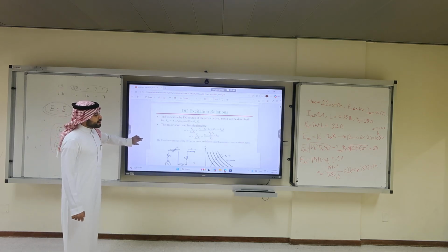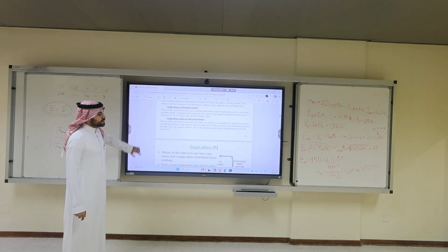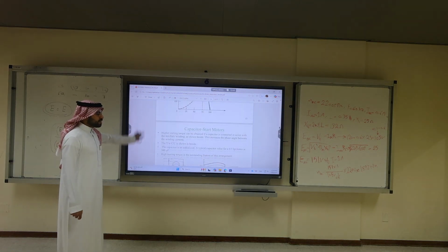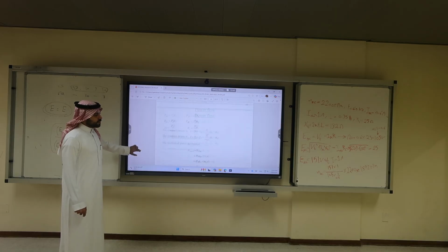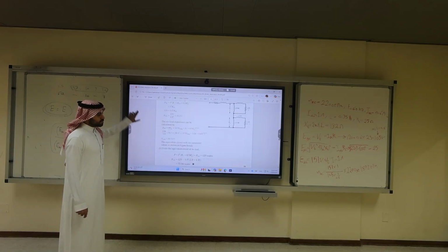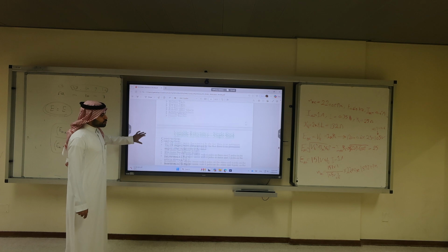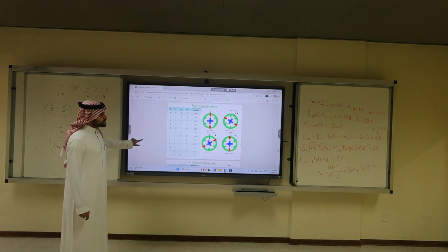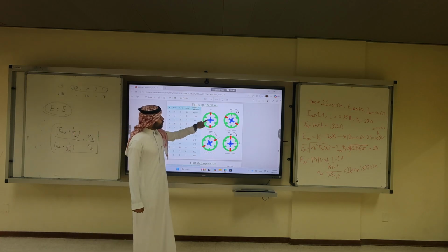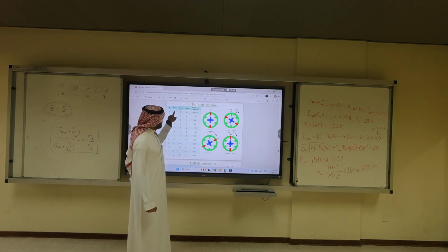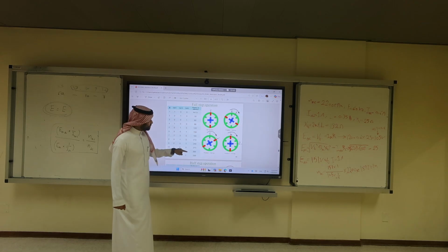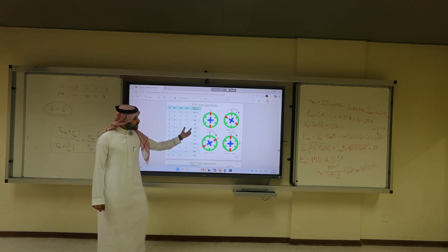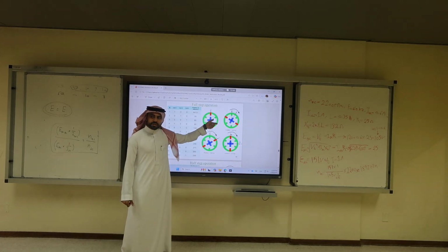So last time we talked about the variable reluctance stepper motor, correct? Did we explain the half angle? No. Last time we talked about the full angle. For full step operation, you only have one coil active at a time. So you have ones here. Every time you add 30 degrees because of that movement.